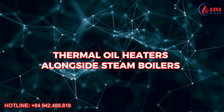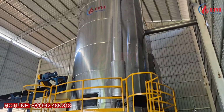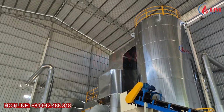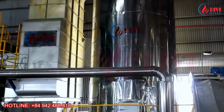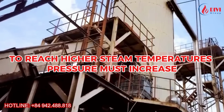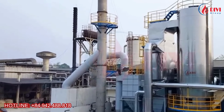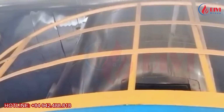Application 7. Thermal oil heaters alongside steam boilers. Alongside steam boilers, another important industrial heating technology is the thermal oil heater. Like a boiler, a thermal oil heater is designed to provide heat for industrial processes. The difference is that instead of using water and steam as the heat transfer medium, it uses thermal oil. So why use a thermal oil heater? Because producing higher steam temperatures requires much higher operating pressures. For example, achieving steam temperatures of 180 degrees Celsius, 200 degrees Celsius, 250 degrees Celsius, or even 300 degrees Celsius requires a significant increase in steam pressure.